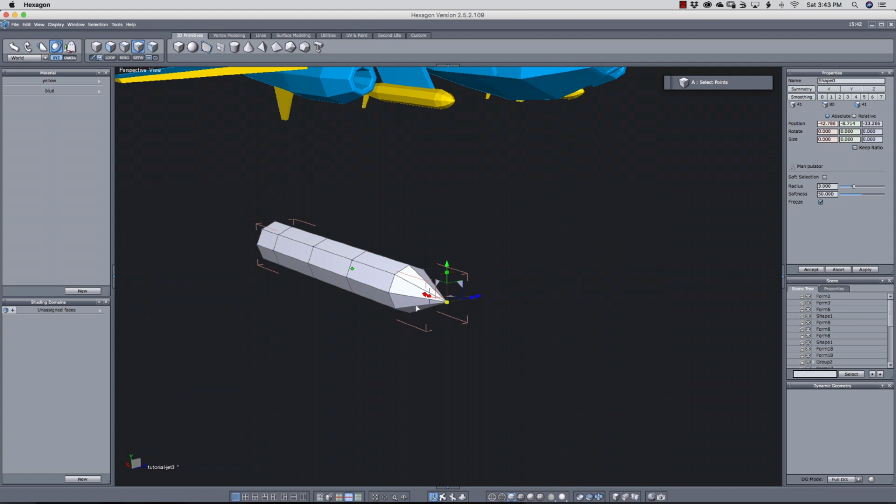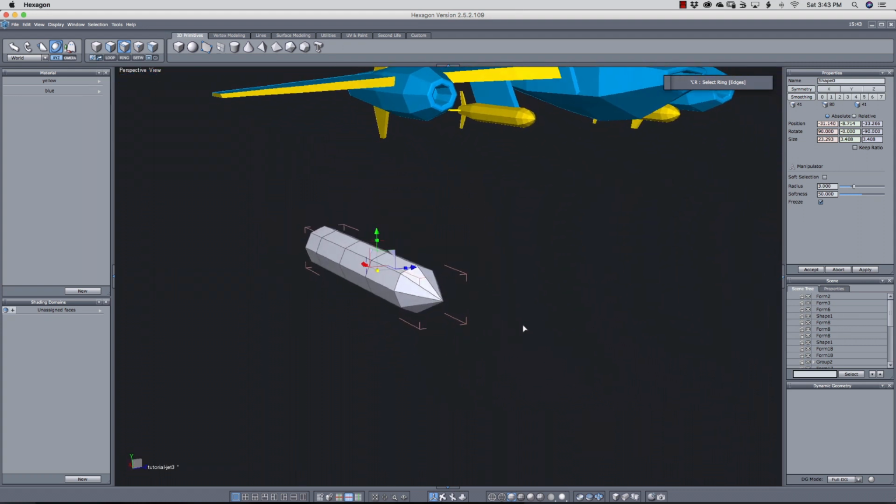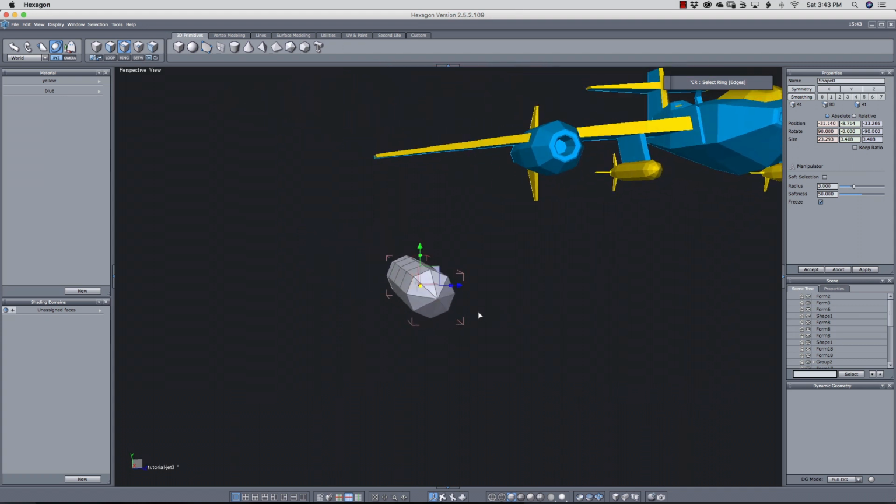And now that I have the basic shape, I can divide this a bit. But look, when I try to ring this, it doesn't work. Why? This kind of shape creates a point that is known as a pole. As you model more complex models, you'll need to manage the placement of these poles. In best practice, you want to have poles only in places where it makes sense. In this case, it makes total sense. We'll need to ring this shape a different way.